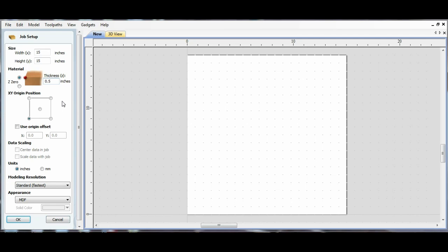The biggest thing with thickness, say I had a 3/4 inch piece of plywood and I put 3/4 inch in here, but it was actually 1/16 inch shorter. I've actually seen 3/4 inch plywood even less thick than that, almost 1/8 inch. If I put that on my CNC machine and zero it properly, it's going to think there's a 3/4 inch piece, but it's going to cut all the way through 1/8 inch through your piece. We have what's called a spoil board on our machine, so that's okay.